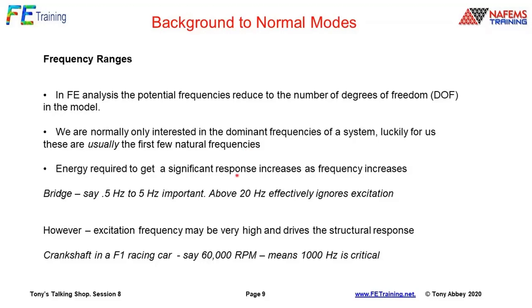The energy required to get a significant response out of a structure increases as the frequency increases. So that is naturally a good thing that works for us. If you've got a bridge, for example, 0.5 hertz to 5 hertz is important. Above 20 hertz, it effectively ignores the excitation. So we just drive to a zero response.